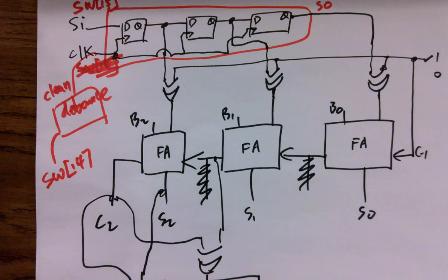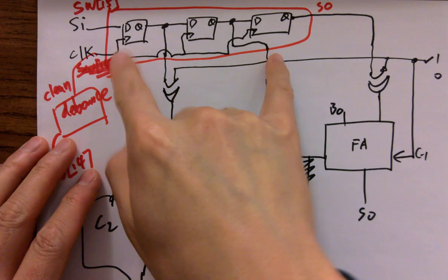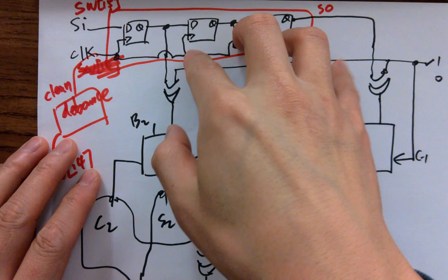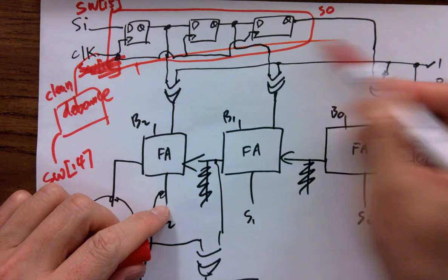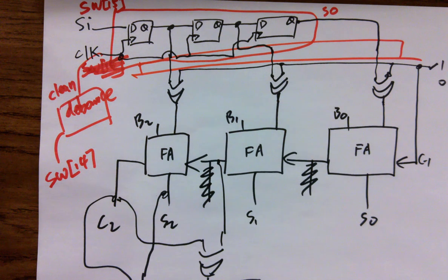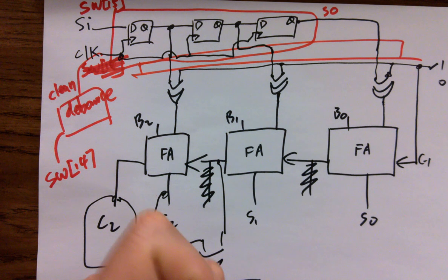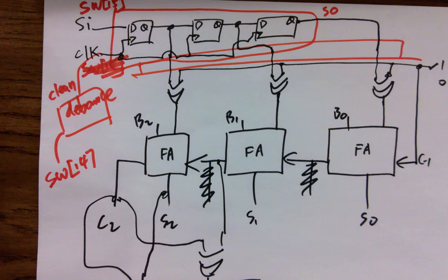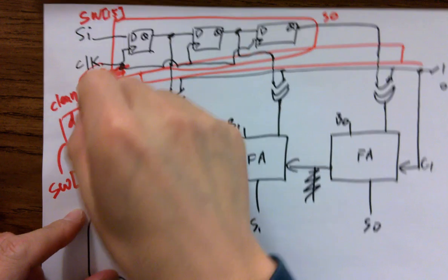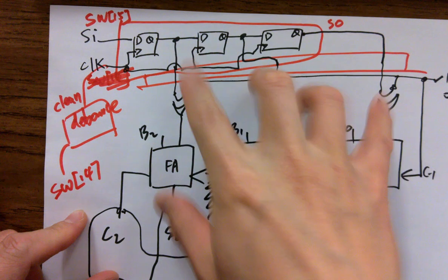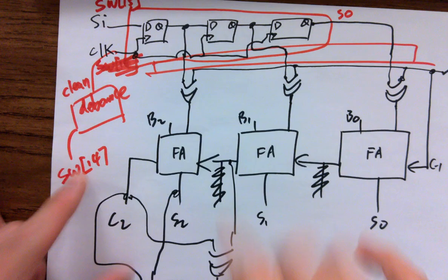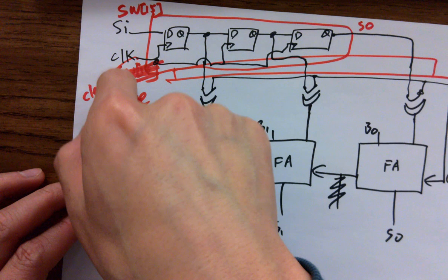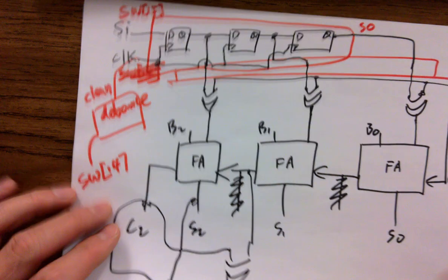Eventually you got 3 inputs, right, and then parallel out because they're already there. You're not actually going to have another control layer. Definitely you can add another control layer only when they are ready, so you don't have any intermediate values. Whenever they're ready, you pump them out at the same time with one more clock. But actually we don't care about that. Whenever you are clocking every single digit in, it's changing the values, changing the output. So whenever you do it for 3 times, after the 3rd time, you know that's the final value. So you have to count how many times you are doing this. Make sense? Yeah. Very doable.